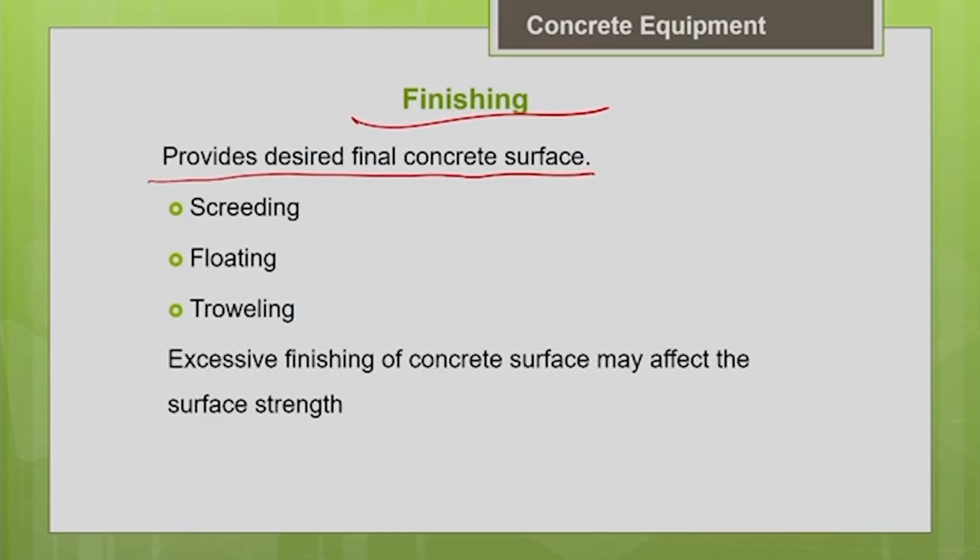But generally speaking, after consolidation, whatever work we try to do with the concrete will generally harm it. That is why after consolidation, we should not do excessive finishing. Very commonly in project sites, you can see finishers try to manipulate the surface of the concrete by adding water and finishing, so that they get a very good surface texture.